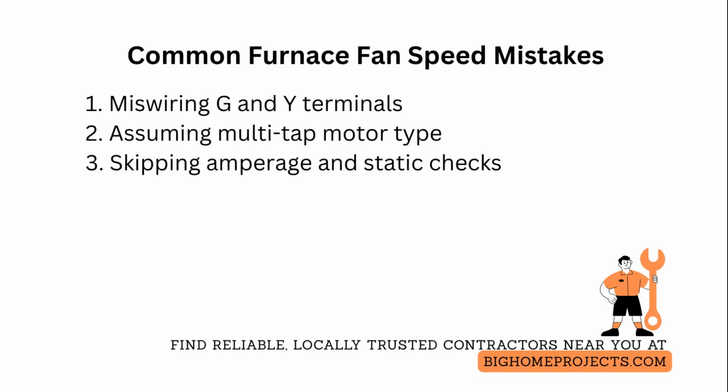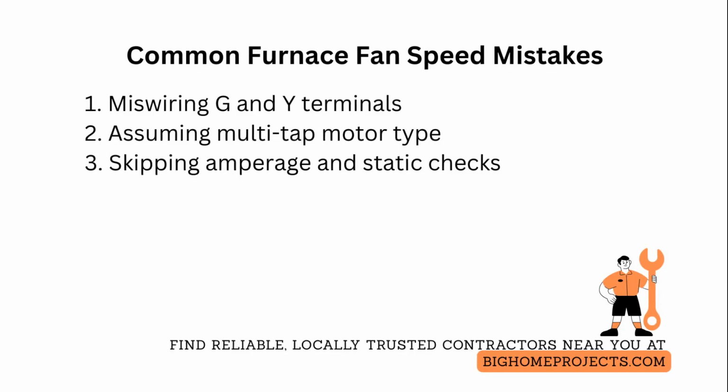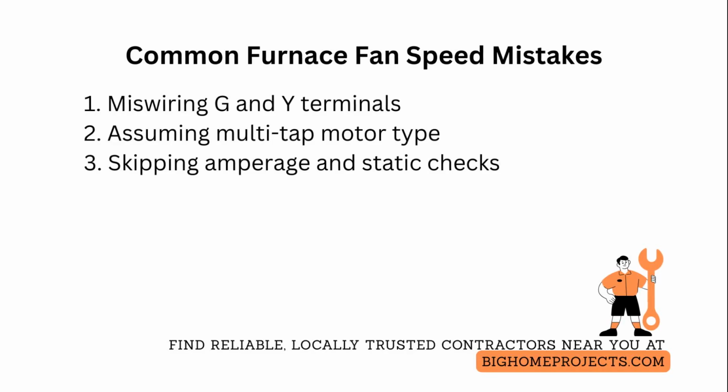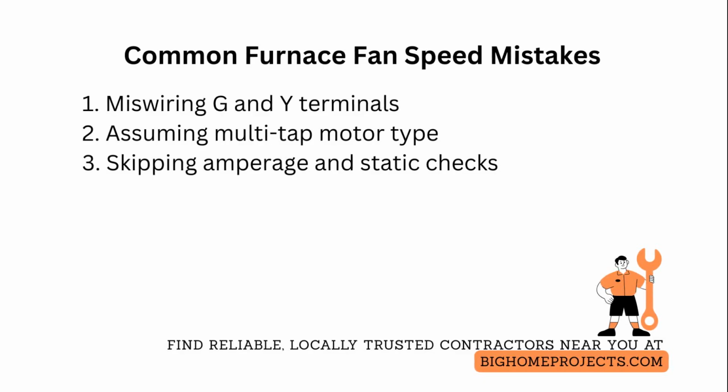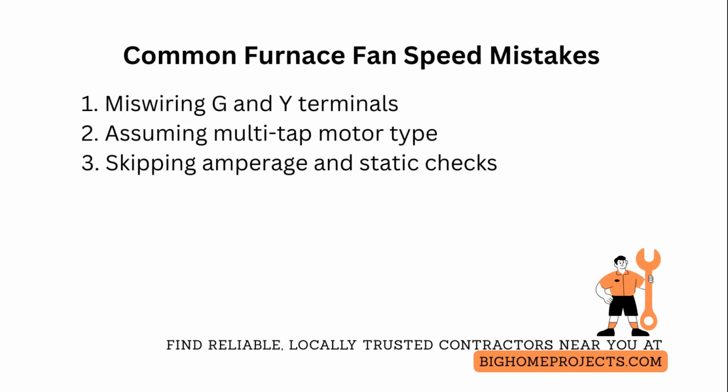One of the other frequent issues is assuming all motors are multi-tap when many modern furnaces use variable speed motors that expect a speed reference signal. Remedy that by reading the motor nameplate and control board documentation and using an adapter harness or the correct replacement control module to provide the proper reference voltage or pulse width modulation.